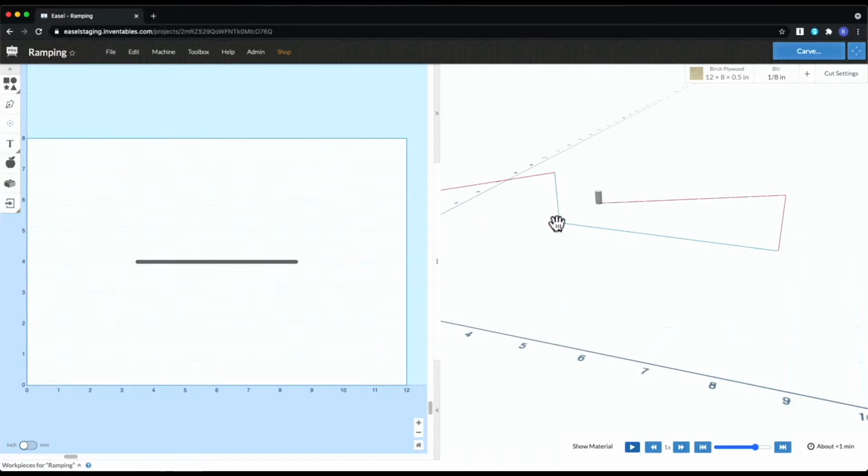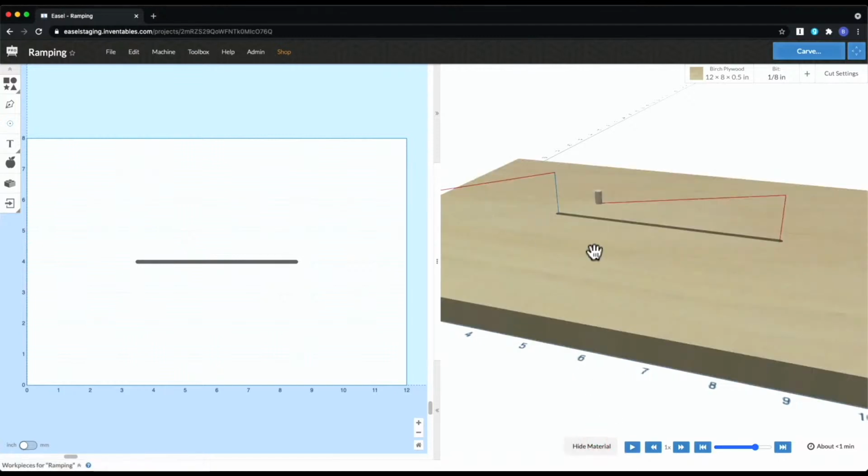For the plunge cut, it's going down straight, so it's really going down at an angle of 90 degrees in relation to the material. Now, what you can do is change the angle that it goes down, because traditionally these style bits aren't really made for drilling, like you would put on a normal drill. These are made for moving side to side. So if you want to increase the life of your bit to keep it sharp, as well as limit the potential of it breaking and even get a stronger cut, then you want to use ramping.